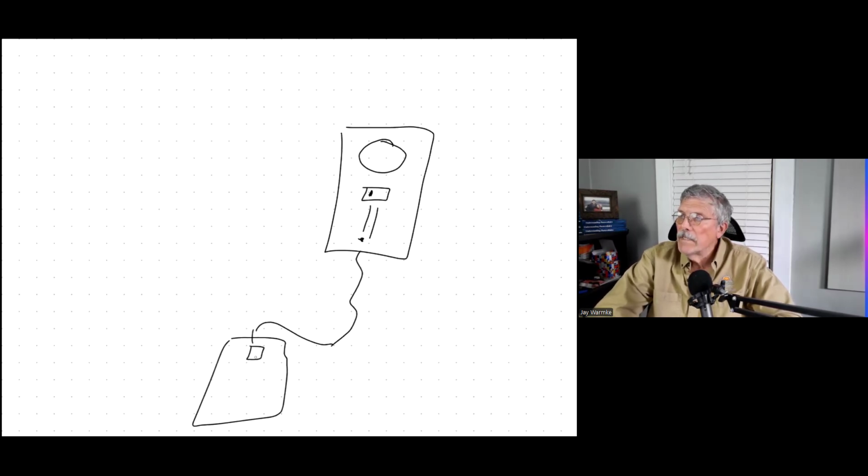So you've basically put in another panel, because these usually have space for four, might be more, double pole breaker locations. This is now your new main. Because these are newly required, if you're putting in a solar array, you might have to install one of these. That's going to require an electrician, but it's not as expensive as replacing your service panel.